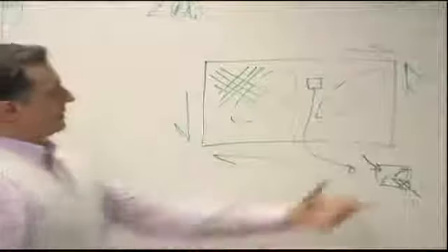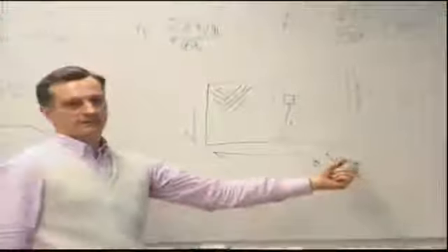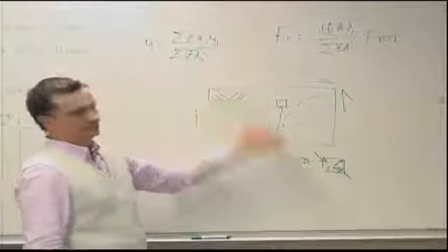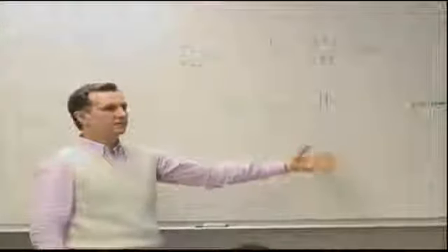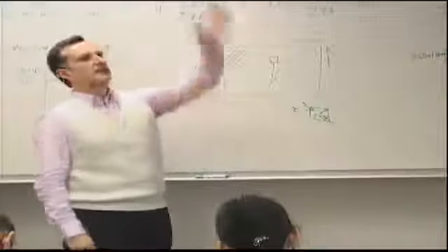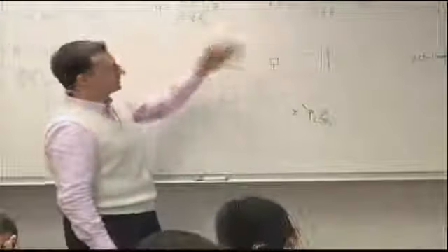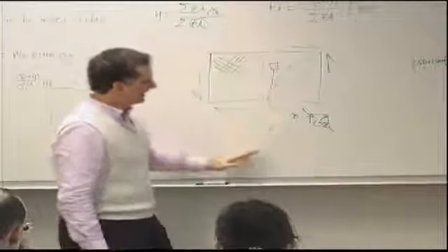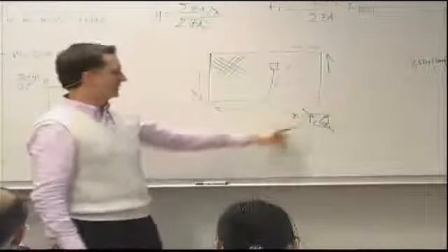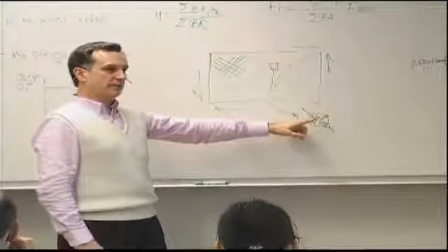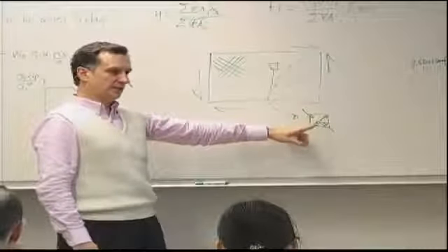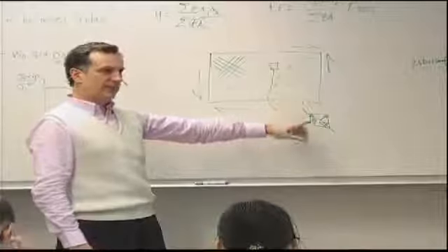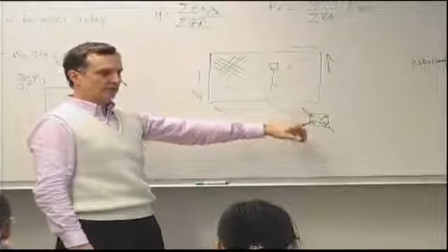So what does the compression part do? It tries to buckle, it buckles the fibers even, let's say, okay, it completely destroys the load carrying ability in compression. But let's think about the tension part of the load. We are putting fibers in tension, and unless we pick a really bad material, that's what fibers are good for, in tension.